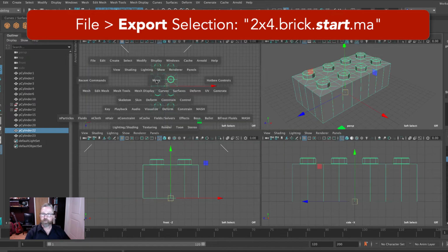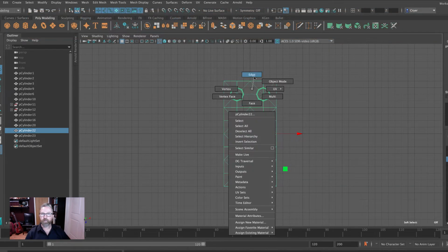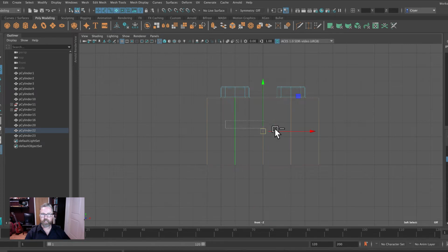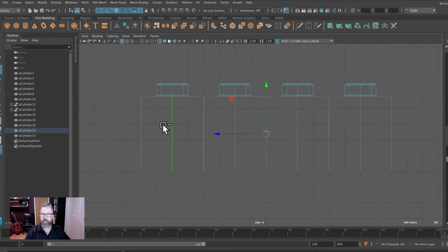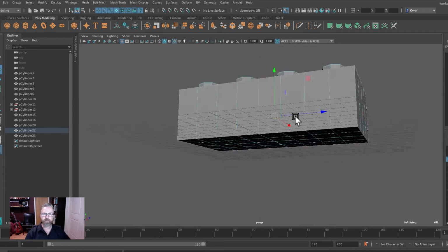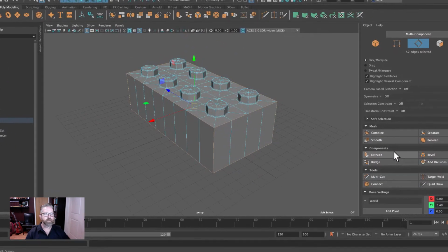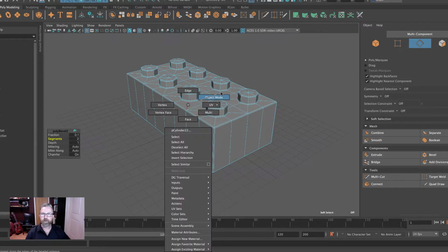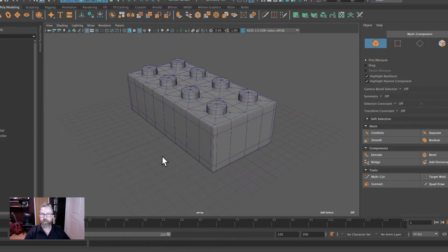All right, so we've got our latest technique where we'll select all of the edges, use our control key to deselect the central edges, and we'll do that in each of the 3 orthographic views. So you can see that it's a relatively quick way of selecting those external edges, and we can come to the modeling toolkit and we can hit bevel, and we know that our fraction is 0.1, and our segments are 2. And so here is our, hit 3 key just to verify that.